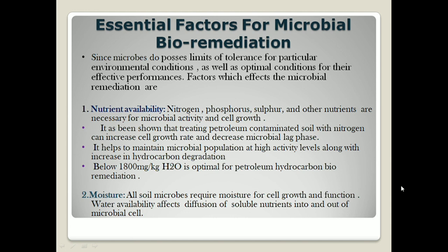It has been shown that treating petroleum contaminated soil with nitrogen can increase cell growth rate and decrease the microbial lag phase, and it also helps to maintain the microbial population at a high activity level along with an increase in hydrocarbon degradation. It is also shown that an excessive amount of nitrogen in soil causes microbial inhibition. Below 1800 mg nitrogen per kg of H2O is optimal for petroleum hydrocarbon bioremediation.